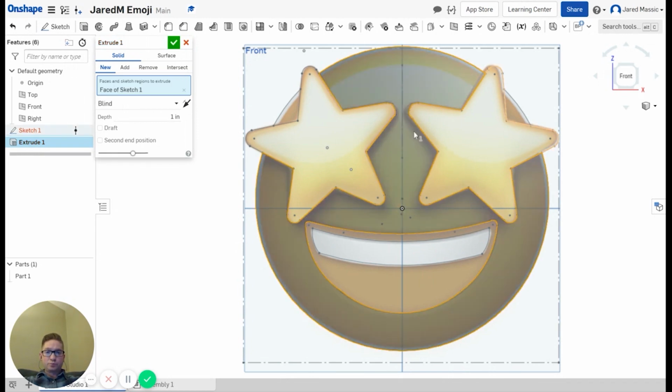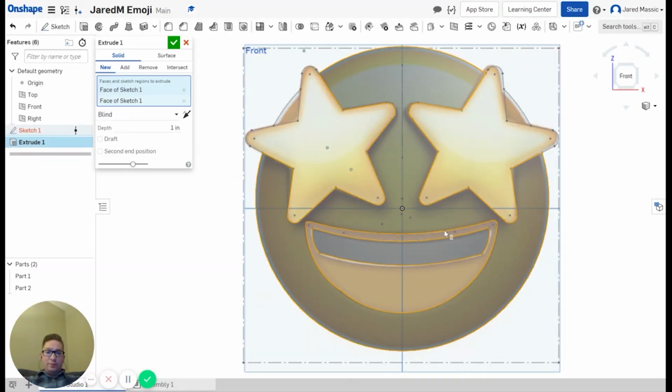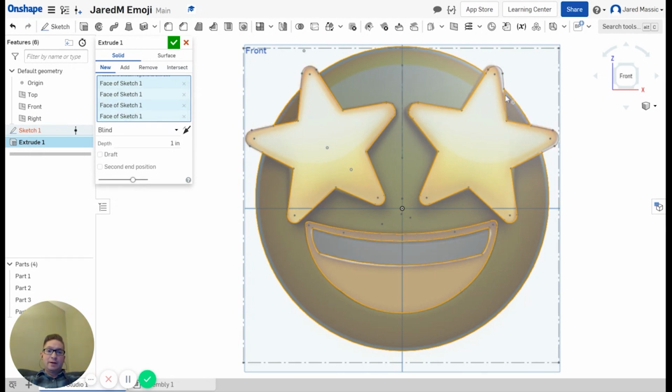Perfect, right? Well, you can see that my teeth aren't connected to my face, and so that sounded funny. It's not going to stay put. If you can imagine this being a solid piece of steel, the teeth are going to fall out when the mouth is cut out. Okay. Likewise, if I extrude over here and I extrude over here, when I cut the star shape out, it'll just be a big wide open.